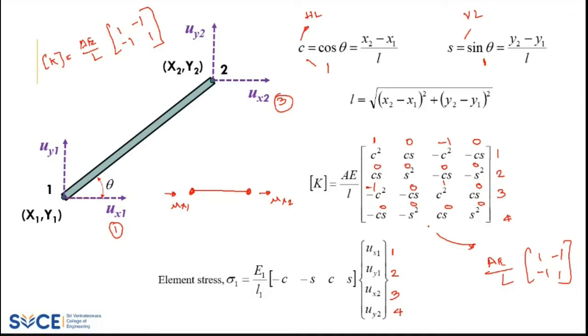But anyway, we are going to apply it in a truss way, because some elements will be like this and others on the other side, and it is difficult to identify the addressing point. So you consider this as a single formula. Either it's horizontal or vertical, you follow it accordingly. One thing you have to notice: for a horizontal line, your C will be 1 and S will be 0, and your length is nothing but the length of the element, whatever it is. And if it is vertical, your S is 1 and C is 0, and the length will be whatever measurement you can consider as the length. So this way you can simplify your formula. No need to use this formula x2 minus x1. Don't apply these things. Directly you can identify.